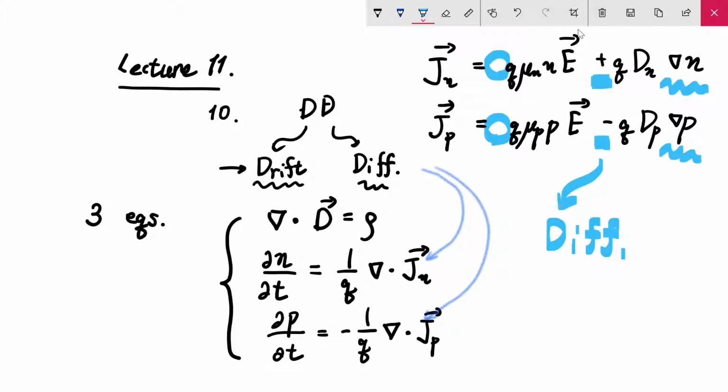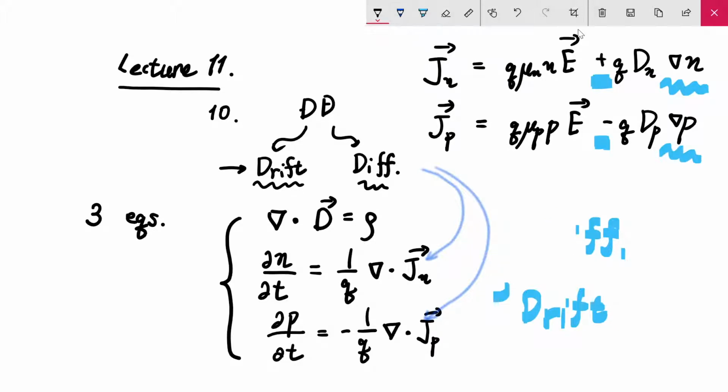So therefore, the same sign related with drift and a different sign in the diffusion related term, so there's a real paradox. But please note that we are not talking about the flux itself, we are considering the current density. So the simple answer is, this quantity is given by minus q times the electron flux, and also this Jn is obtained by positive q multiplied by the hole flux.